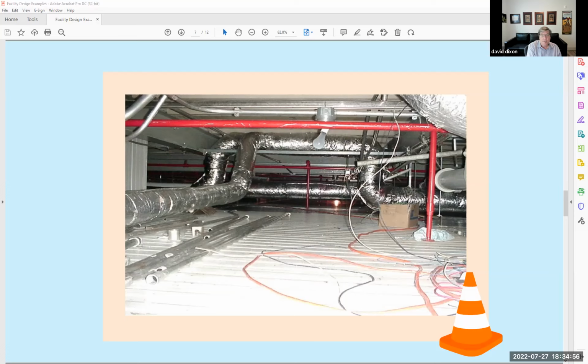There's just a lot of coordination. 3D design has helped a lot in this, but you see it's got a solid beam. Sometimes that's an open truss, and you can run conduit, you can run fire protection piping through it. We can put ductwork above the roof and drop the ductwork only vertically through this interstitial space. There are about a dozen tricks when you're height constrained in your interstitial space, but it all requires planning.